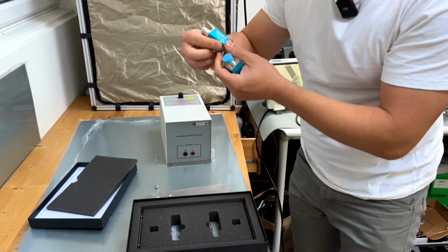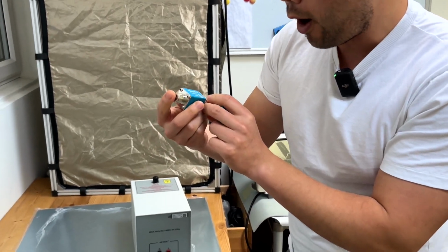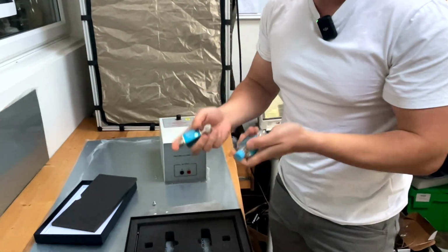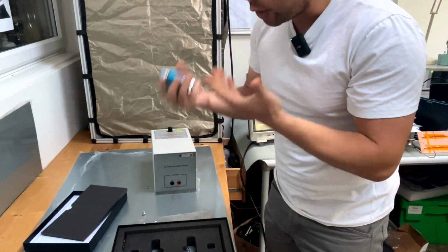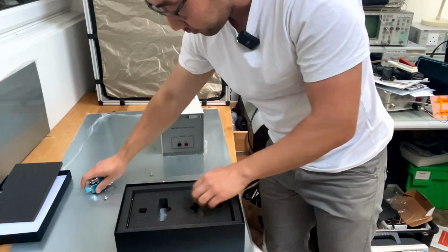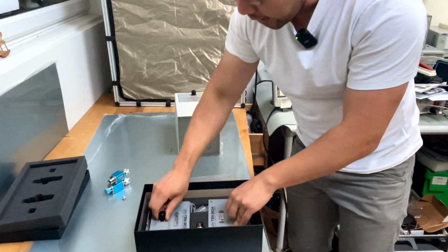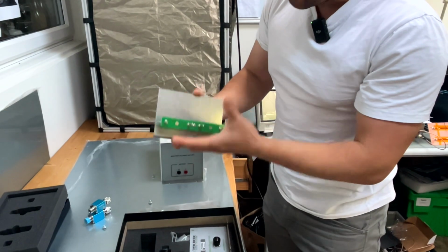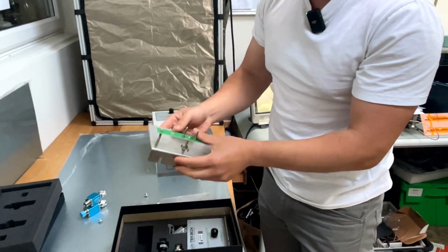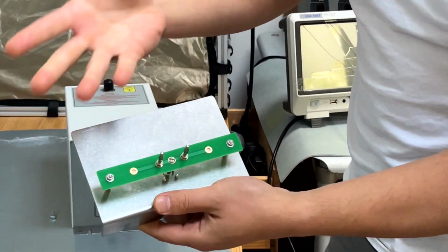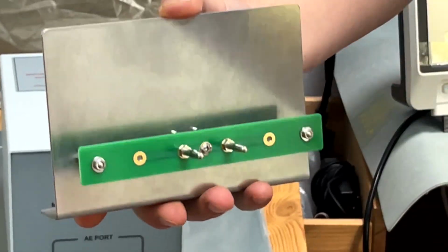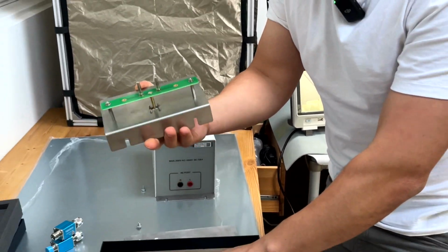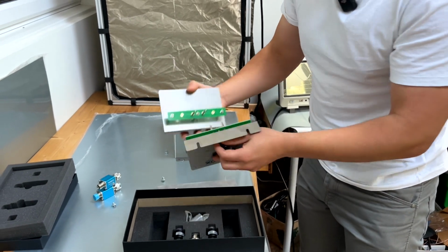And 2 adapters, and this adapter is called a 50 to 150 ohm adapter. As we explained, 150 ohm as a common mode impedance is very important. Therefore, for calibration, we need these adapters. And what's inside here is this adapter plate. As you can see, this is an adapter plate designed for calibrating an M2 type CDN. Therefore, there are only live and neutral, or positive and negative inputs. For M3, you will often find 3 pins here. So this is designed for and used for M2, and you need 2 of these.